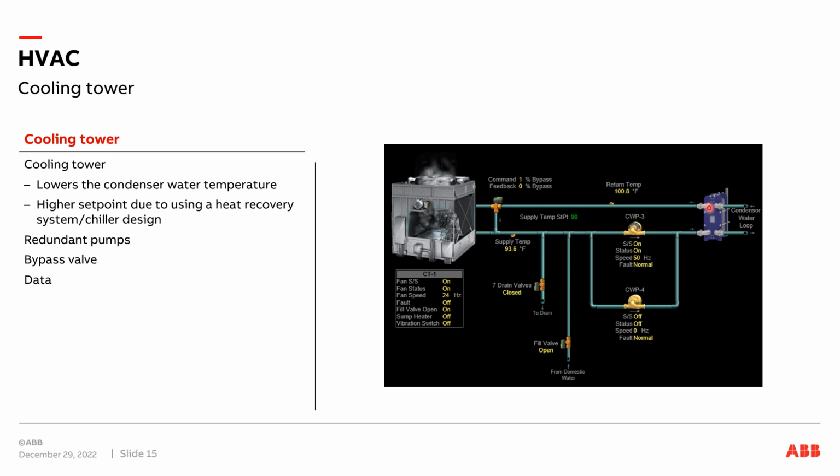So we've got this condenser water loop. It runs a little bit hotter than normal because of that whole heat recovery system we had for using the VAV reheats with our condenser water going into our hot water system. So it's a little hotter than you might typically see. But you've got this 100-degree water that comes here, falls down that waterfall, and starts to cool.